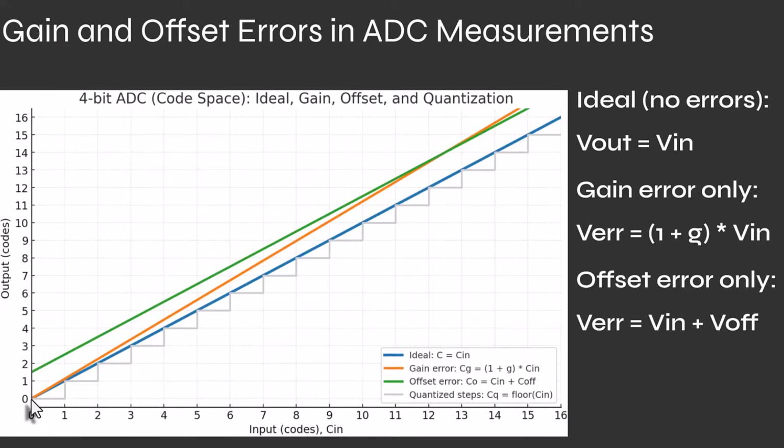If we assume that these are our only static errors and we do this two-point calibration, the only thing you're left with then is the quantization error. And if you're not familiar with quantization error, go to the anabit.co Data Converter U blog where you can find a tutorial on quantization error. Now, of course, there's other error sources. A lot of them, though, are more noise-based.